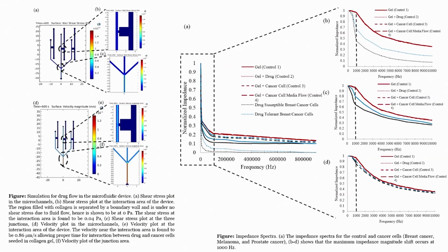Now, always remember, whenever you want to fabricate a microfluidic chip, you need to perform simulation. Why simulation? You need to understand how your flow is. To understand a microfluidic chip in detail, you need to understand a lot of things, like the Reynolds number, what the shear stress is within the microfluidic channel, what the velocity is, and whether the flow would be smooth or not. So, a lot of things you need to understand, and that is why we perform a simulation.